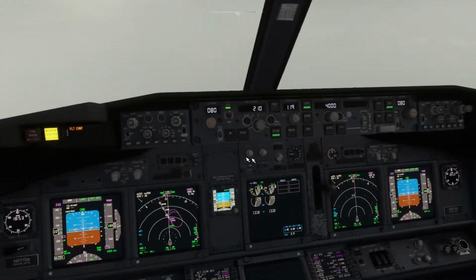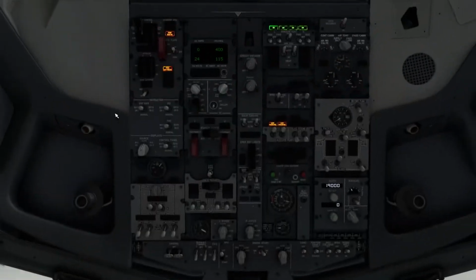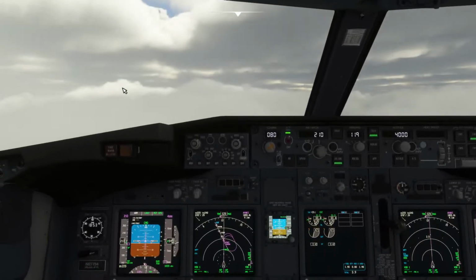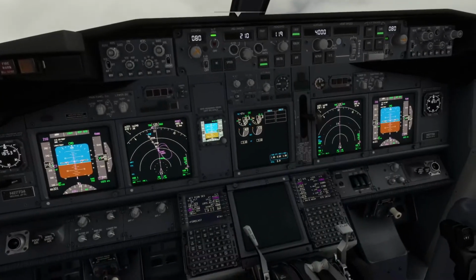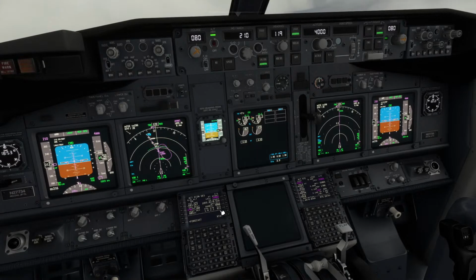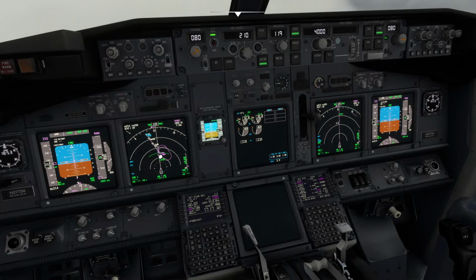So master caution, flight controls and hydraulic. Let's see what we have. Yeah, I didn't change anything. Sometimes because of the pitch changes, we are going to have intermittent amber lights. So let's see with 210 if it matches 800 here. We need to descend at least 800, if not we extend the speed brakes. And we have the altitude trend vector also there, reaching 4000 before Avaki. Okay, we can do it.